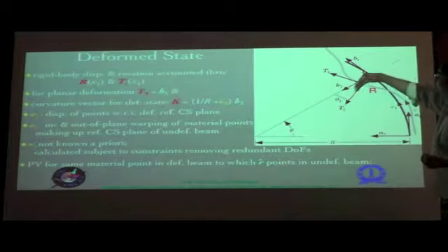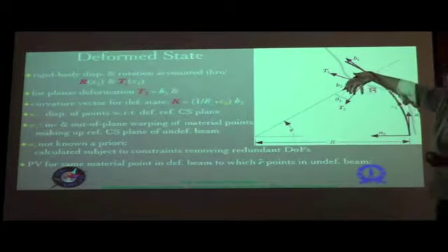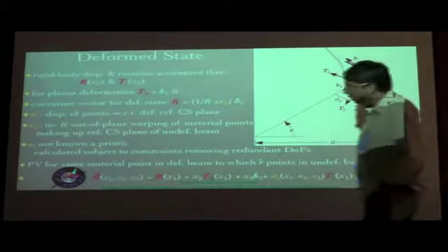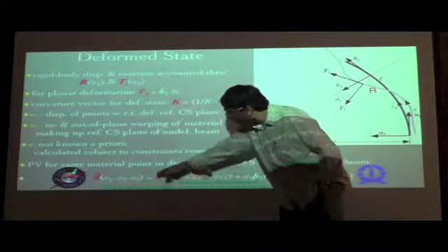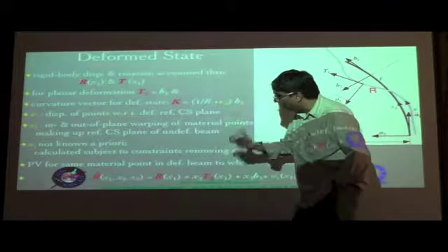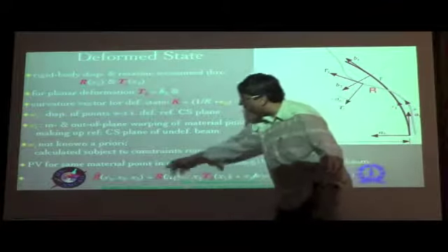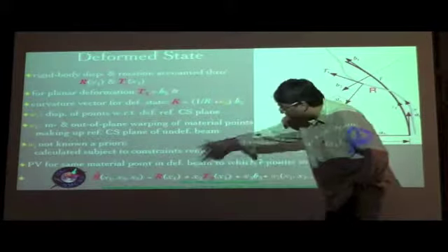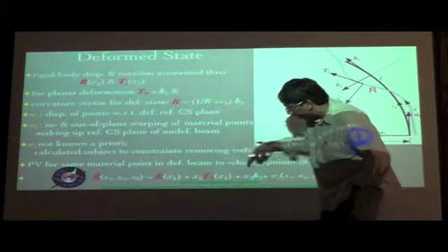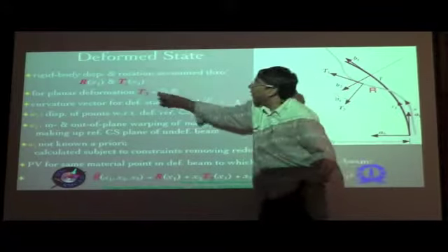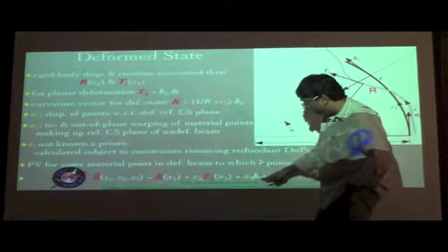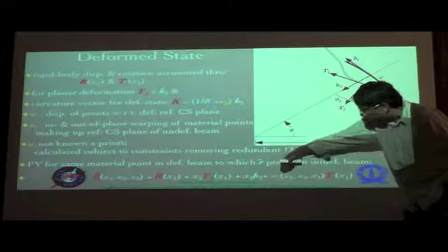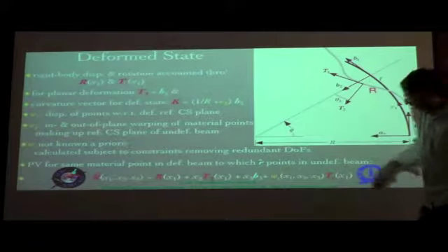Obviously that should depend on the rigid body translations, the rigid body rotations and the warping variables, all of which are involved. And that position vector, as in previous examples, is given by R hat is equal to, first track down the reference curve and the reference cross section on which it belongs. Then you know where it has gone because of the rigid body translations, and then because of the rotations which are involved, you have x2 t2 plus x3 t3. But once again we invoke the fact that t3 is equal to b3, so we can substitute t3 as b3 over here. So that's the only difference from what we have been doing earlier on. And of course you have the w_i components along the big T_i as usual.